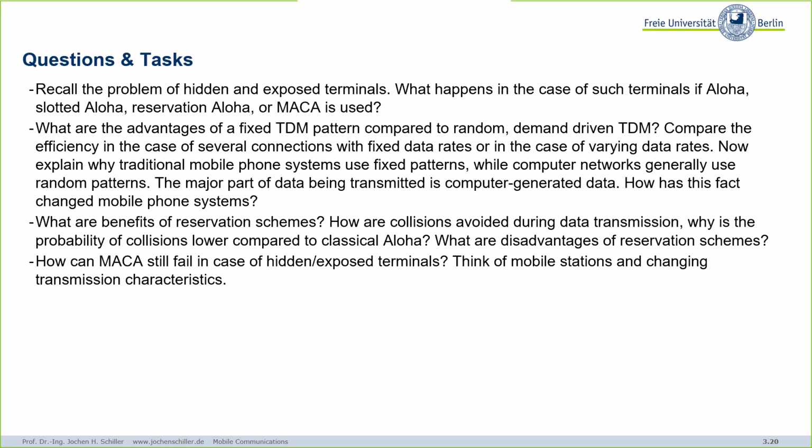Yeah. So the classical ISDN telephone, for example, generates a permanent fixed data rate of 64 kilobit per second. Okay. And then we know if we compress this, etc., then we can easily squeeze this into a repeating pattern of time slots. That's the classical scheme we have used for many decades, TDM schemes in telephone.